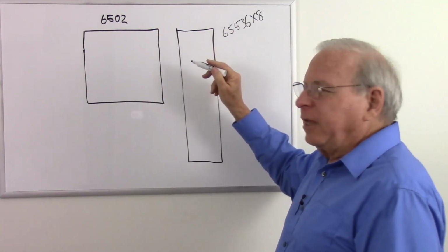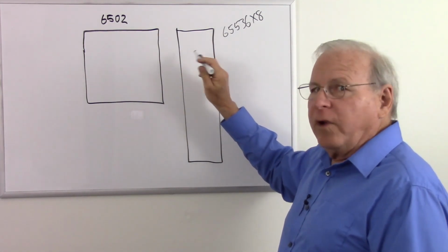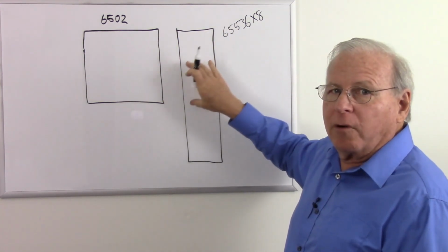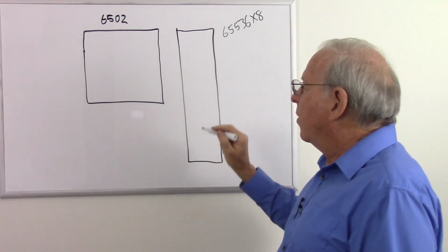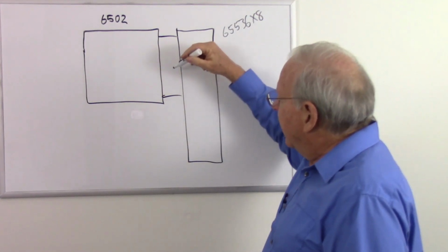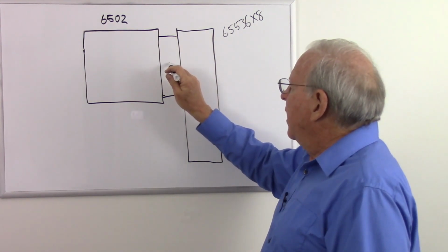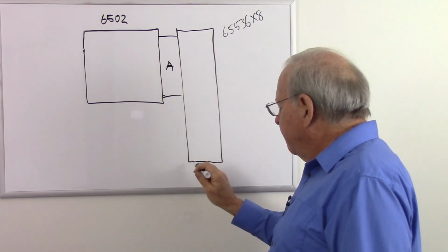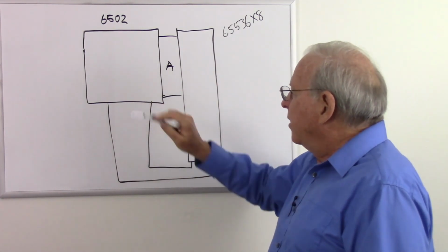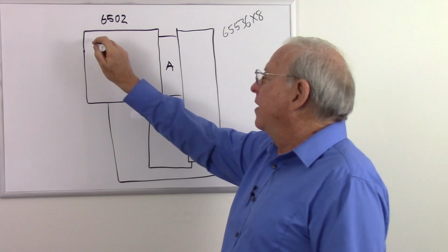And let's say it's completely full with all the memory, including the read-only memory that starts up the computer, and the other memory we can put programs into and store data and whatever. And there's some wires, 16 of them to be exact. 16 wires called the address bus. I'll just put an A there. And then 8 wires called the data bus that went in somewhere else, and I'm going to oversimplify this a lot.